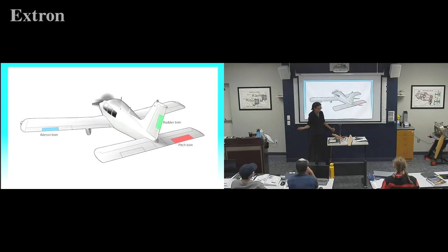172s have it also. It's just a little piece of metal that you can bend because aircraft have left turning tendencies, so they bend it to help turn the aircraft to the right. But it's set because you have a set engine, and an average way that it operates.